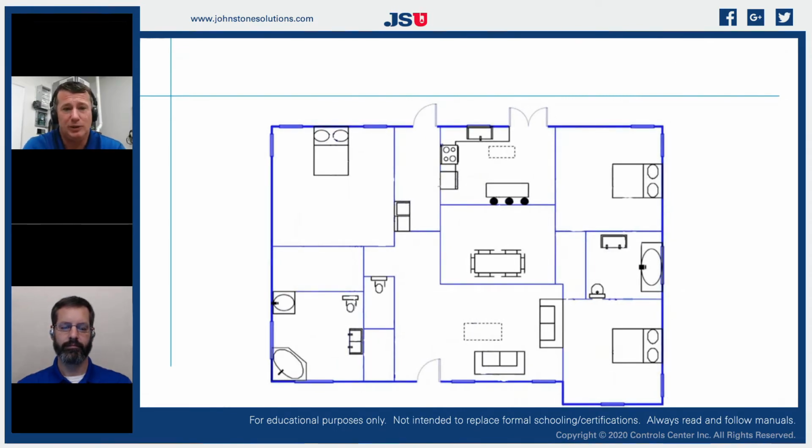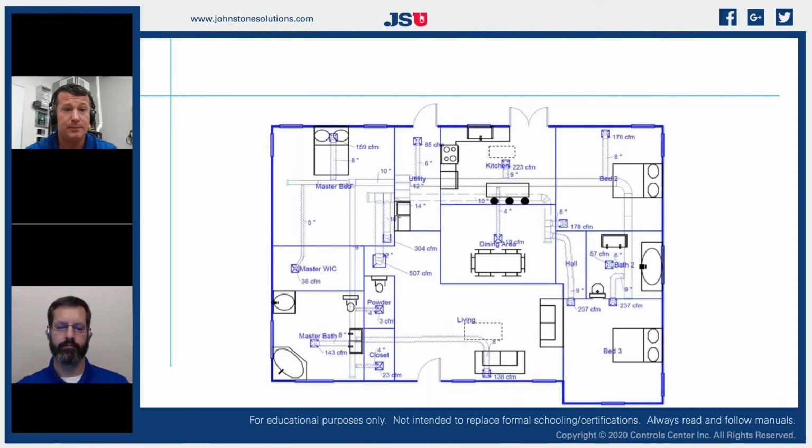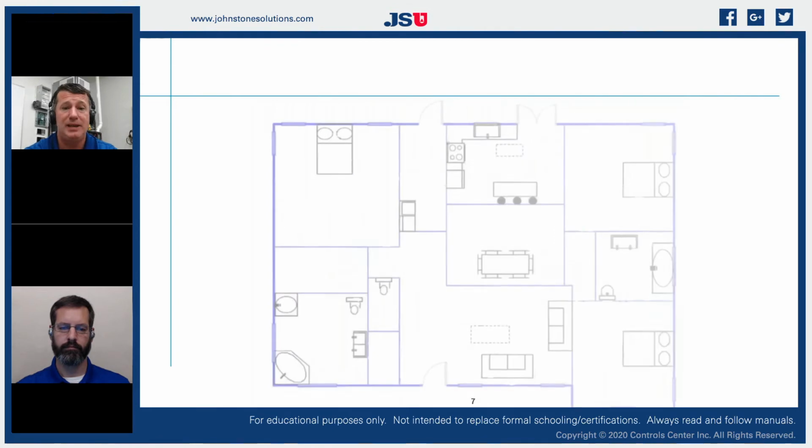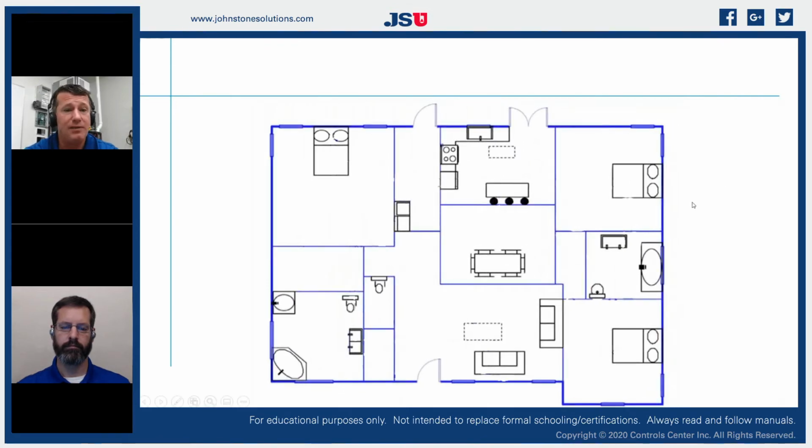So what are we doing with load calculation? Well, we're going to start with a structure, and the goal is to end up having equipment and properly sized ductwork. To do that, we have to start with very basic fundamentals. We have to look at our total structure and the construction of that. So we're going to be looking at outside walls, windows, and doors.